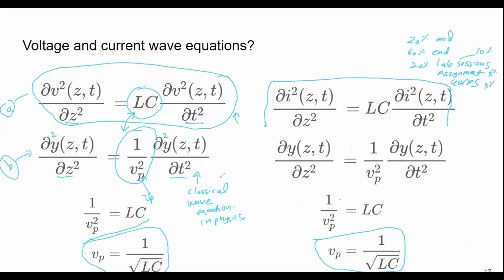By taking the Kirchhoff's voltage law and Kirchhoff's current law equations of the circuit diagram, I derived the equations for the voltages and currents across the transmission line.